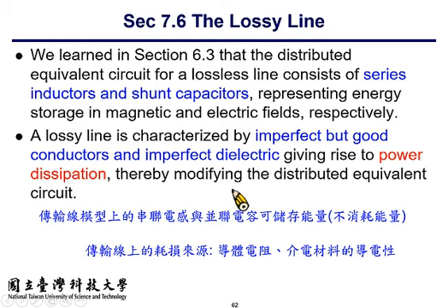The signal only experiences the change in characteristic impedance, the change in propagation velocity, such as due to the change of material. So for transmission line circuits, one important characteristic is you cannot simplify the so-called equivalent model.